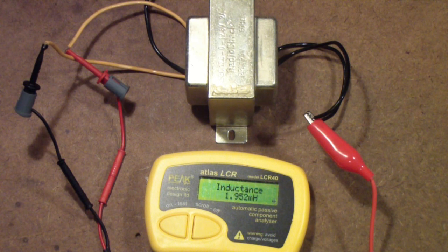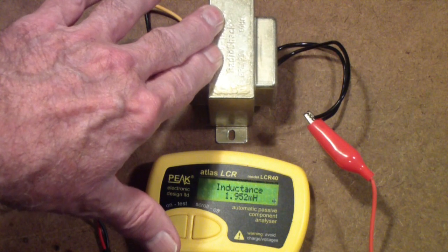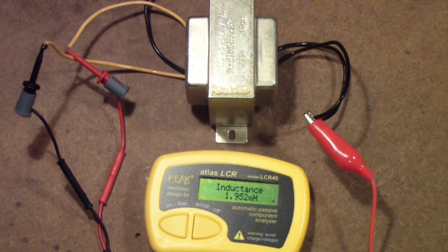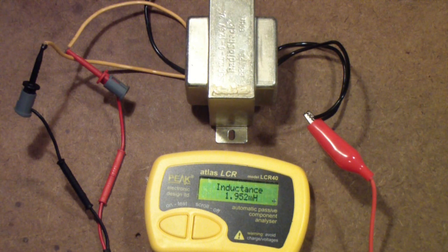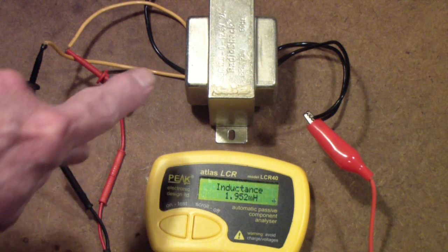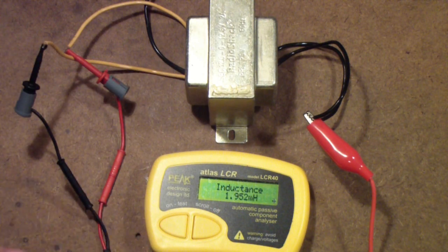So the ratio of inductance in this transformer is about 15:1. And that is of the primary inductance to the leakage inductance. Now that generally is a good measure of the efficiency of the transformer. So 15:1 means that 1/15 of the power is wasted in the transformer. And that's only approximate. One reason is this transformer was designed to operate at 60 cycles. This meter measures at a kilohertz and so on. But basically you're getting a measure of how much the leakage inductance is in this transformer.